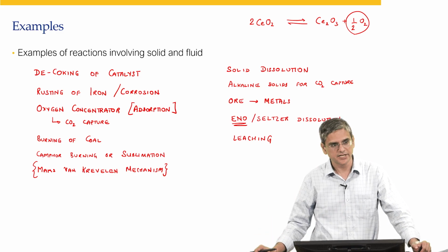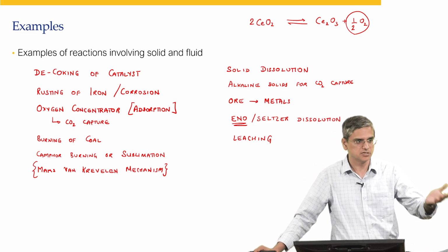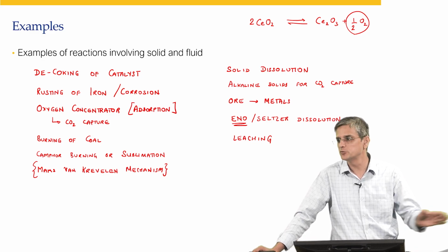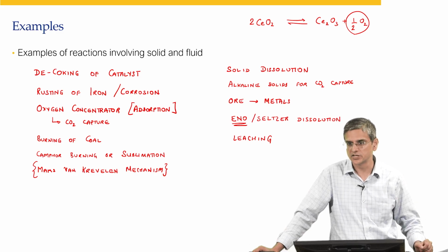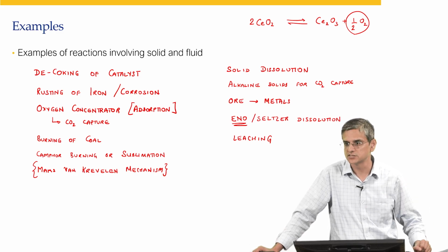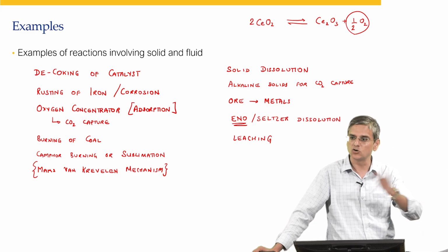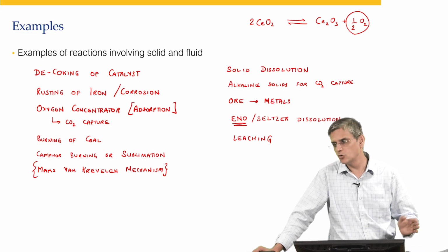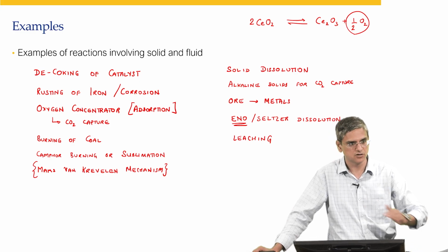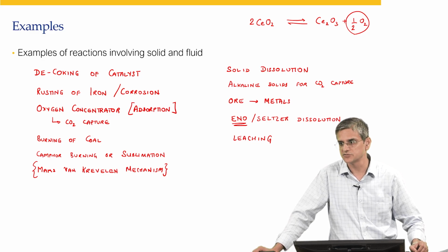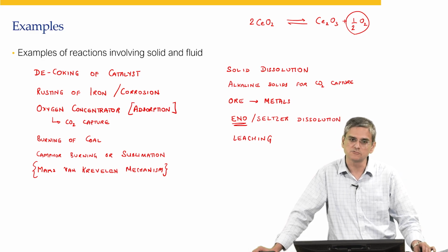In case of aluminum it looks gray in color, in case of brass it looks green in color, and therefore you periodically need to wash it away with Brasso or equivalent stuff. Whereas when it comes to silver, it is the sulfides that are formed that lead to a black coloring. Oxide only gets rid of the shine on the surface, because it's a very thin layer of oxide that is formed, and it's a very slow reaction process, whereas sulfide formation is a relatively fast reaction process.